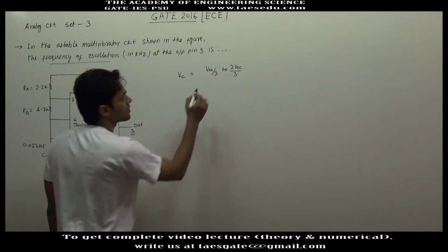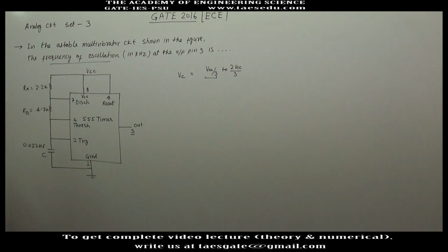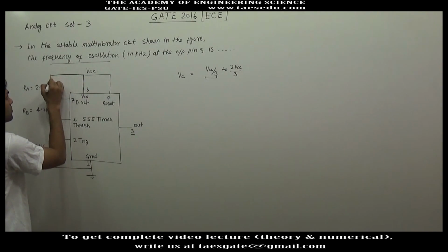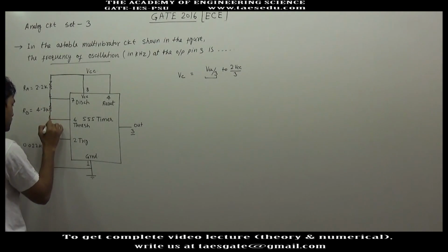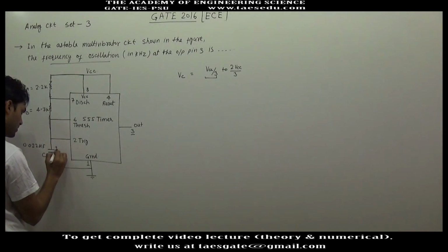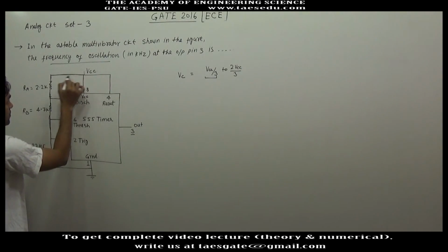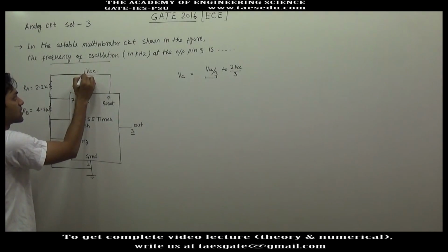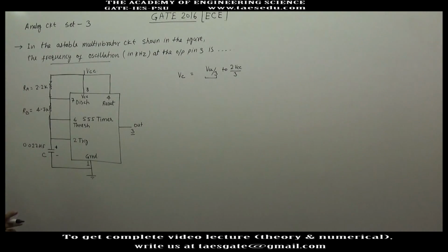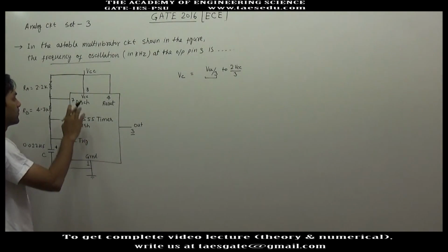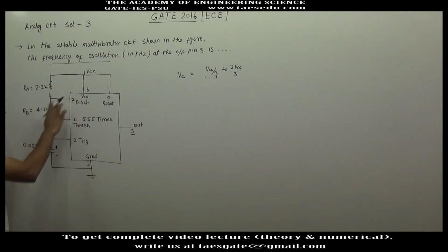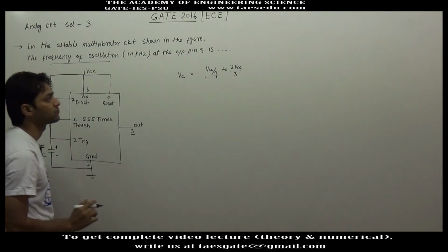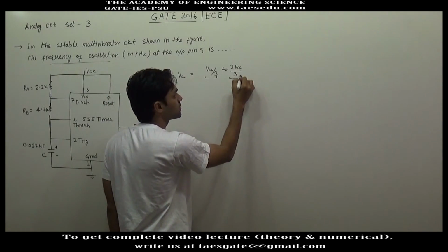When the capacitor voltage hits the minimum value, it starts charging and it charges through VCC. So the charging path is current will flow through RA, then RB, then capacitor, then ground. So the capacitor will charge towards VCC, the steady state voltage of the capacitor. If it is left to charge through VCC for infinite time, mathematically infinite time, the steady state voltage will be VCC.